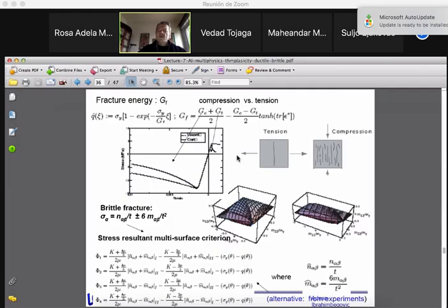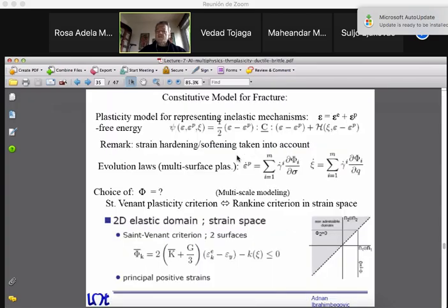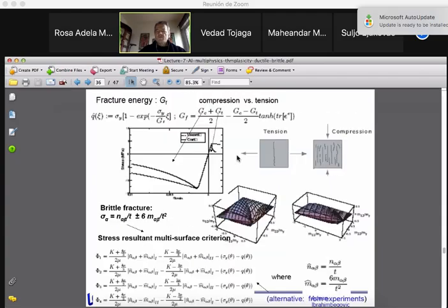And then for the bending part, we took a linear distribution, and as soon as the maximum stress or minimum stress reaches the value of the yield stress, we then assume that this is a breaking. This way, we don't take into account some kind of distribution, but even these are very brittle structures, and basically it's not much of an approximation. So from the strain, I can do the stress, and from the stress, I replace this with the stress resultant. So at the end, I recover from these two surface plasticity in the principal strain case, I recover four surface for the membrane bending, and so on and so forth. So that becomes a full surface plasticity computation that I could do.